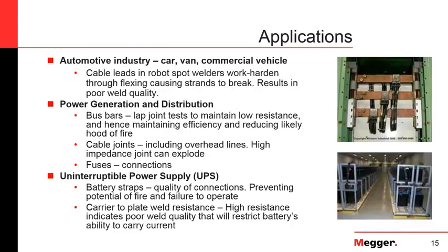Now, this is a very interesting application on battery systems, on UPS systems. The battery cells are linked to each other with conductor bars called straps. These bars are subject to vibration, changing temperature due to the charging and discharging processes of the battery, and also, of course, to chemical corrosion. If only one of those straps in the system fails, then our whole bank will fail.